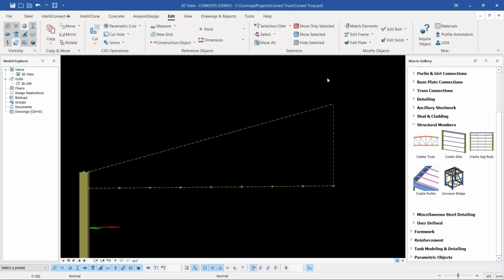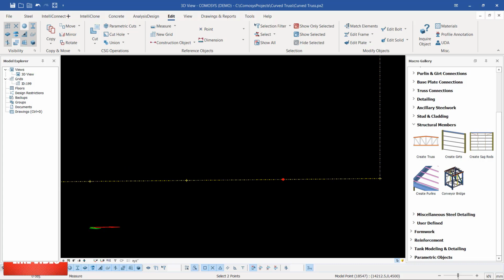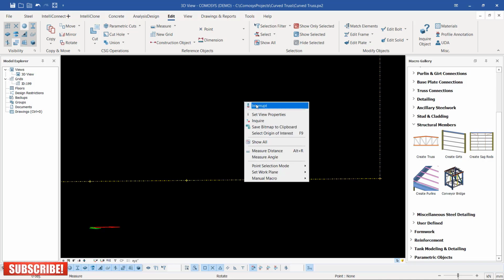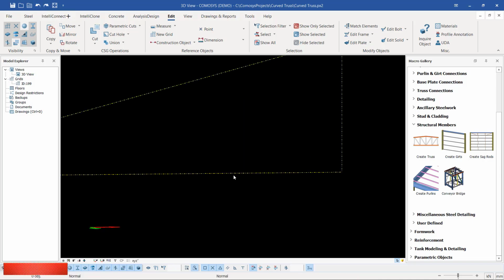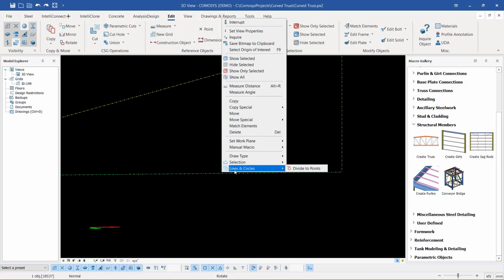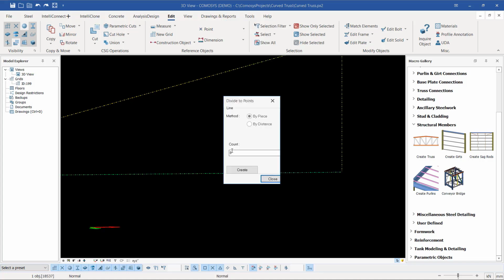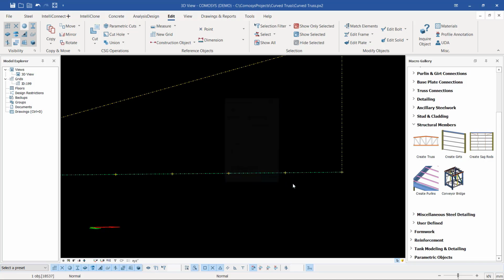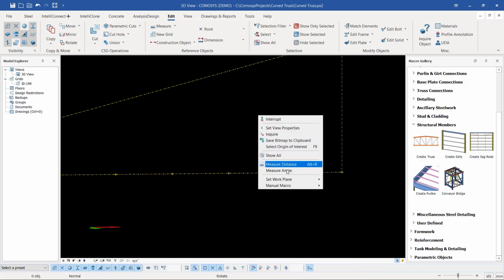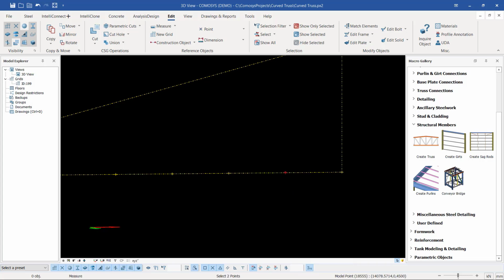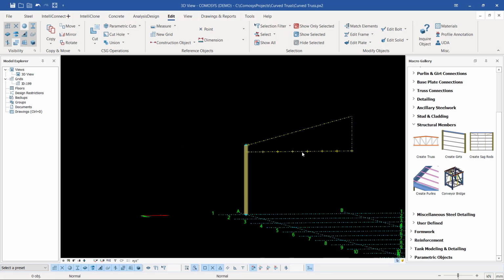Then first of all, left click to terminate that command properly. Then I'll come to right click, then pick on the distance. Let me just check the distance from this end to this end. This is 937. 937 is so close. So I'll undo that, select this line by left clicking, then come to lines and circle, divide that. Let me just take this to 7 counts and click OK there. So let me right click once again to check that, and I'll come to distance and check that from that point to this point. This now how much? This is now 1071. Not bad.